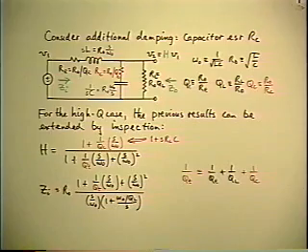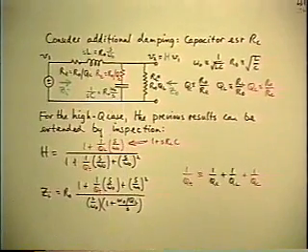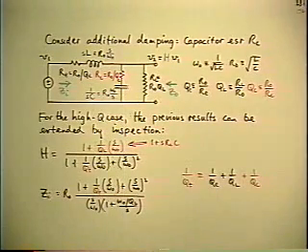Now the payoff of all this is the next step. A still more complicated case, which is the loaded RLC filter with the presence of yet a third damping resistance in series with the capacitance, which in real life, of course, is associated with the ESR of an electrolytic. Again, this is, of course, particularly relevant to the power supply case.